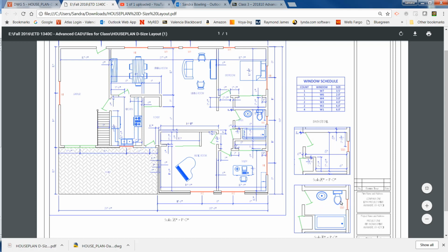down here in the viewport. So you'll need to go to the Design Center and bring in the toilet, a sink, and a bathtub. You'll also have to create the design. Right now, the area in this detail for the bath is blank, so you have to draw this wall, this wall, this wall, okay? And you'll dimension it out.